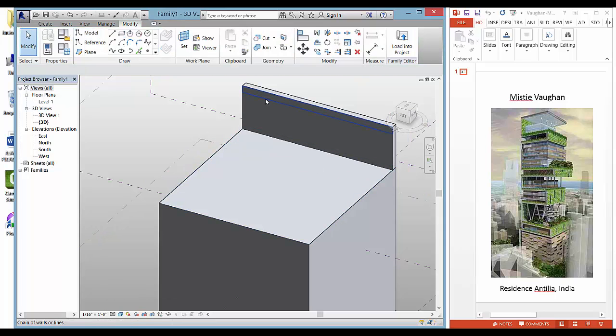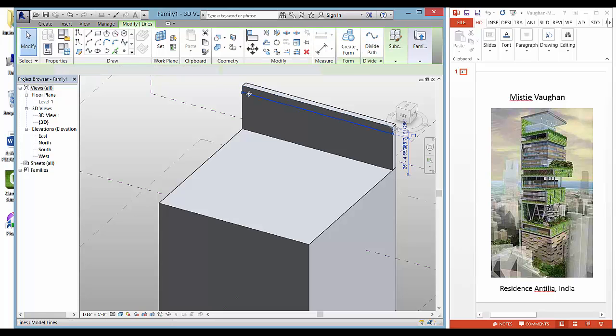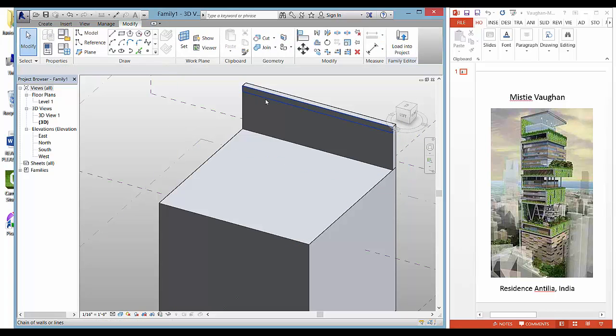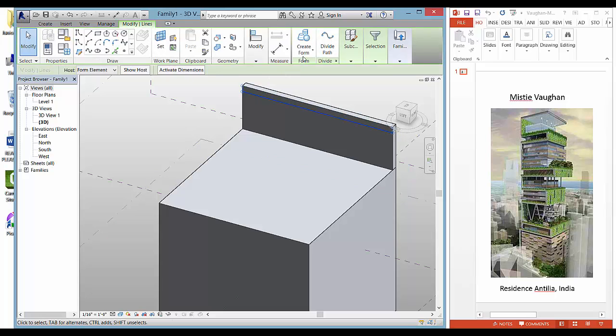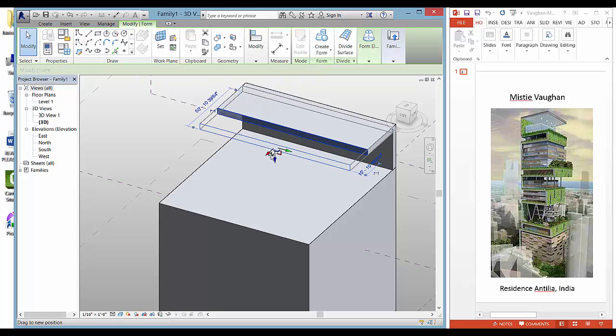My favorite tools in AutoCAD for 3D modeling would be the press pull, and the concept of drawing right on the face or the surface of a model like we are here. Several programs have borrowed concepts from others and kind of changed their names.